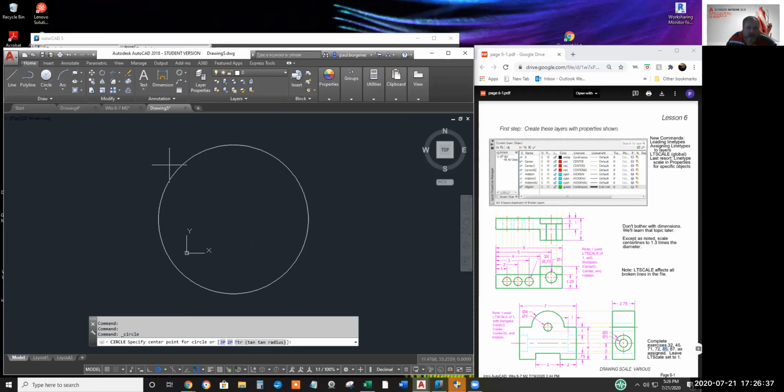Circle center diameter, hover on the circumference, snap in the middle. The small circle in the middle is 45 and hit enter. The base is 35 units below the center of these circles. So I'll draw a line, hover around the circumference and send it 35 down.